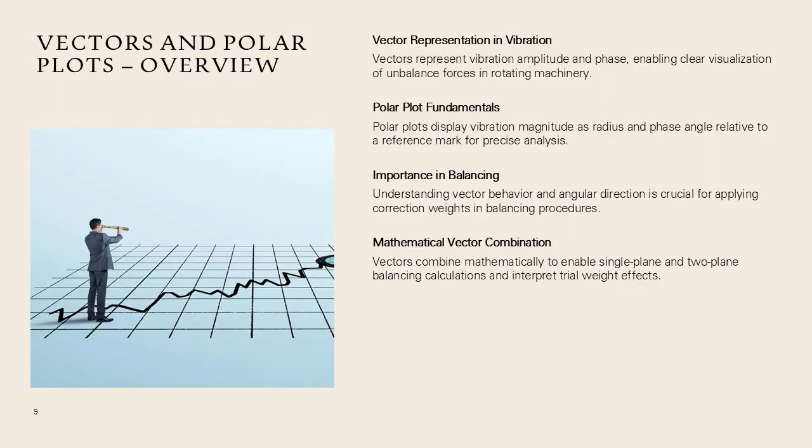This slide introduces vector representation in vibration analysis and balancing. Vectors express both the amplitude and phase of vibration, enabling precise visualization of unbalanced forces. Polar plots show vibration magnitude as a radius and angle as phase relative to a reference mark.